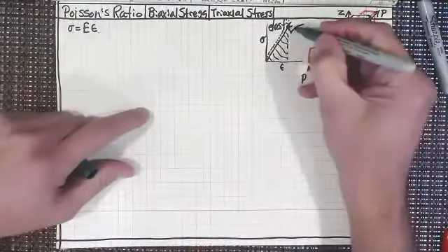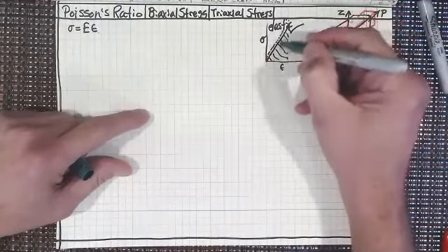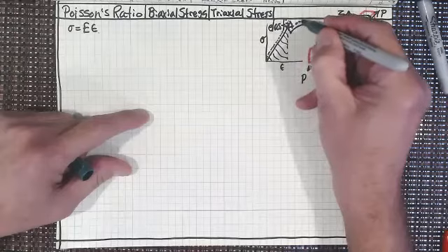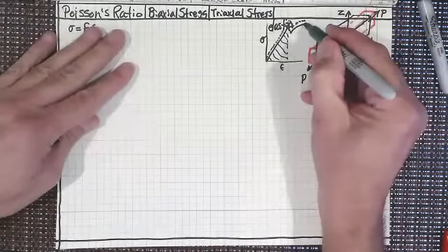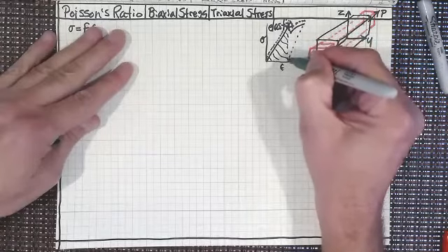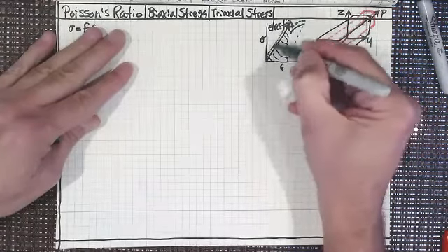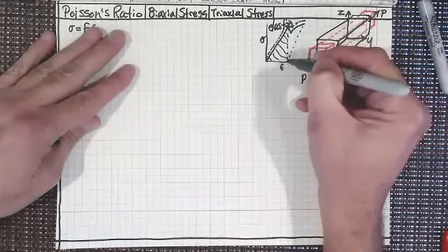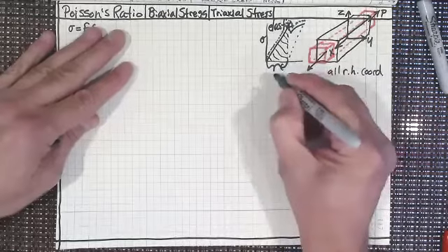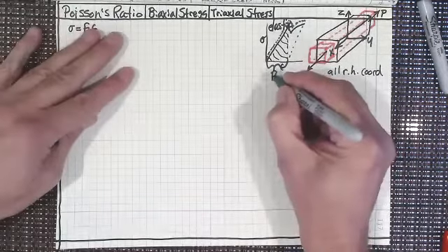But what happens if we go into the plastic region? If we go into the plastic region and start to stress it there, when it comes back, it comes back along the first elastic region, right? So then there is a permanent deformation.